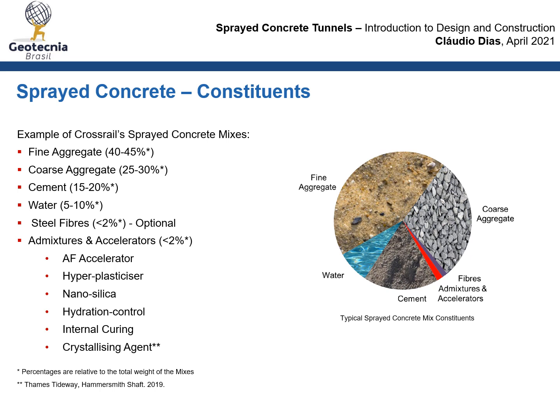These may include alkali-free accelerators, hyperplasticizers, nanosilica, hydration control elements, internal curing elements, and lately crystallizing agents to make the shotcrete more impermeable.